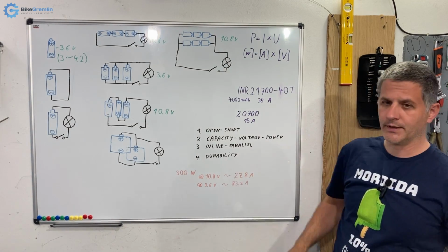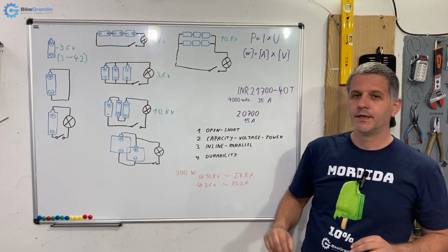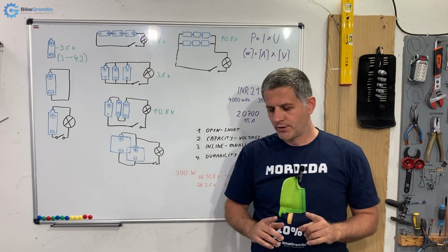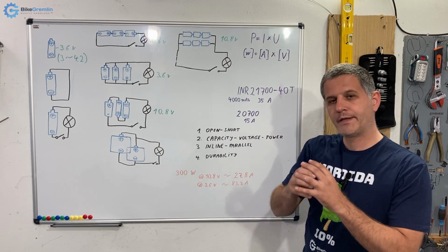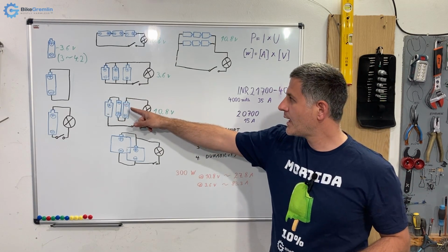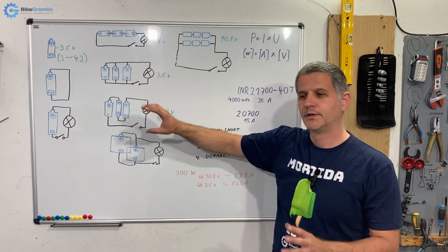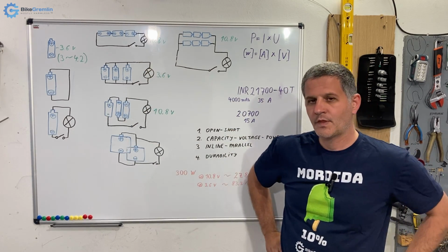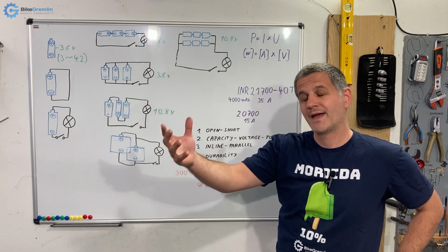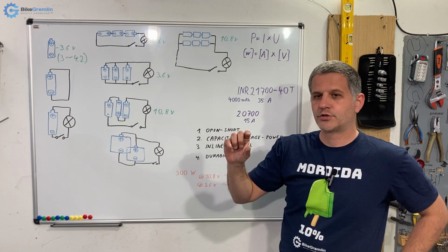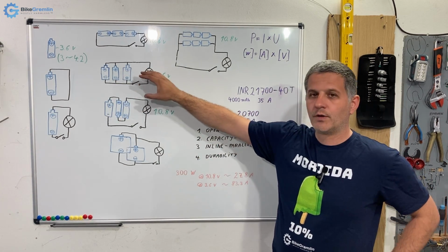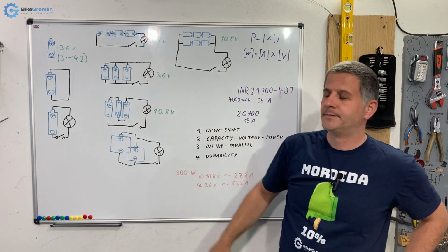Now I will discuss durability. As I said in the beginning, you don't want to overcharge or discharge your batteries too much. Generally, when you have a battery pack, you usually have a certain number of cells packed either in line or in parallel, or both, depending on the set. Now your charger is usually with high quality tools and the appliances. The chargers and tools have smart electronics that make sure that each cell is charged equally and discharged equally, regardless of how they are connected.